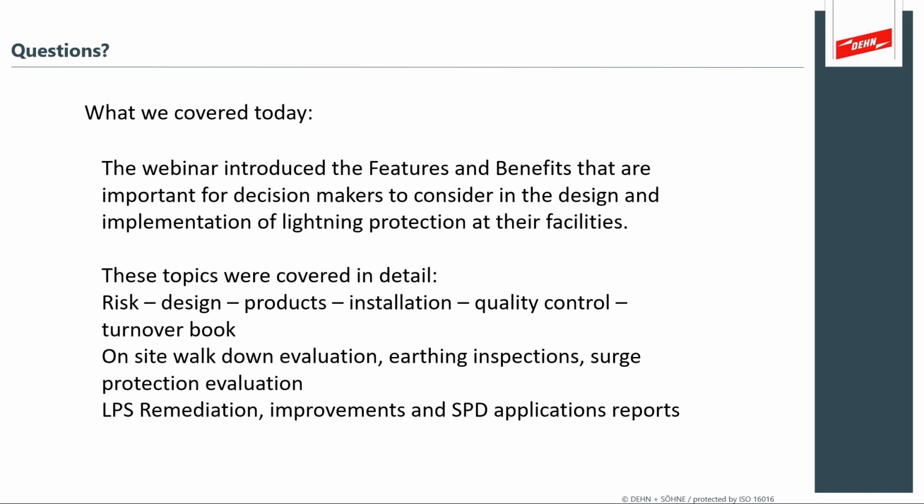Mark, did you mean it's necessary to install both a class 1 and a class 2 at the point to protect equipment? For example, for motors, just next to ground level, isn't a class 1 only sufficient? Yeah, there's a lot to say that a class 1 would still be sufficient at that motor. In many of our applications, the customers are concerned about their motor systems. They've had experience with insufficient SPD applications, and so that was one of the reasons our customers were particularly concerned about installing both Type 1 and Type 2 at their motor systems.